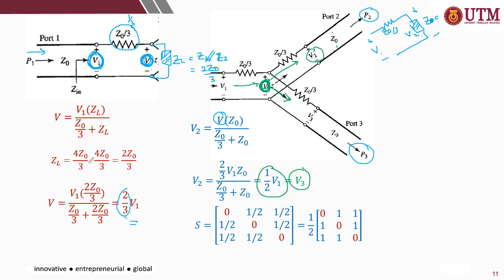And so here you know that the power at the output port, S12 and S21, is equal to 0.5 or 1 over 2. So the S matrix can be listed as: this is S11, so the system is matched, so S11 equals S22 equals S33 equals 0, and S12 equals S21 equals 1 over 2, because the system is reciprocal. So the matrix can be further simplified to this.